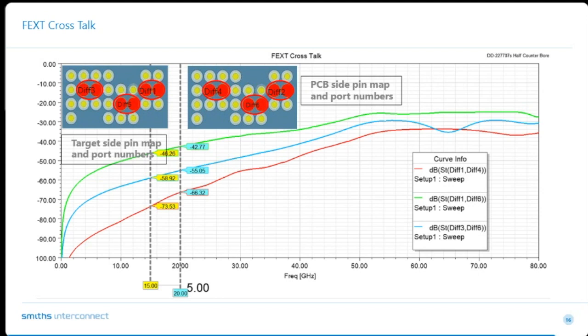And if it doesn't meet the customer requirement, we do this for every socket we're qualifying, correct? Yes. If we have a challenging insertion loss or return loss target we need to meet at a particular frequency and we're seeing some spikes, then we can tweak the cavity structure a little bit to smooth out the response and get the best possible signal path.